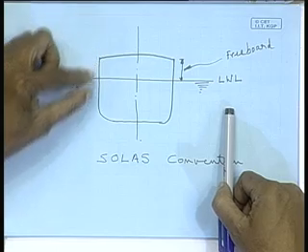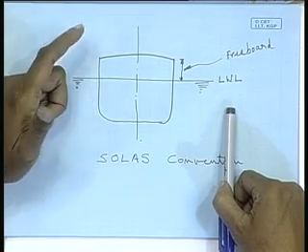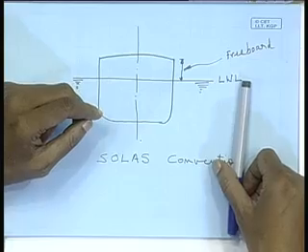But in case of LNG and LPG carriers, it hardly sinks to any draft unless you really load a huge amount of cargo, because the density is very less, of the order of 0.5 or so, right. So in the process, in an LPG carrier, like here I have drawn, only a little bit is above the water, most of it is below water. In an LNG carrier, it can be otherwise.